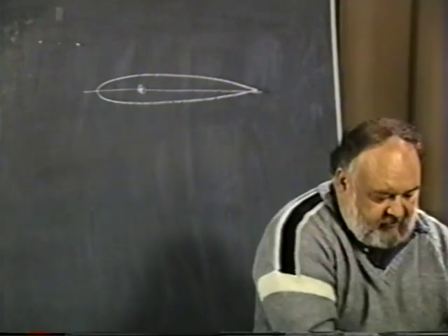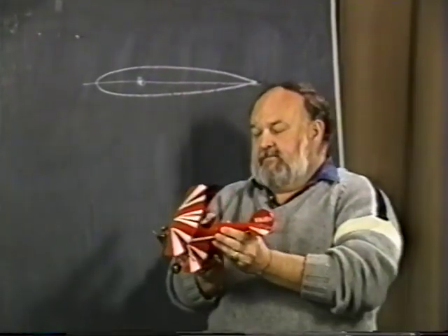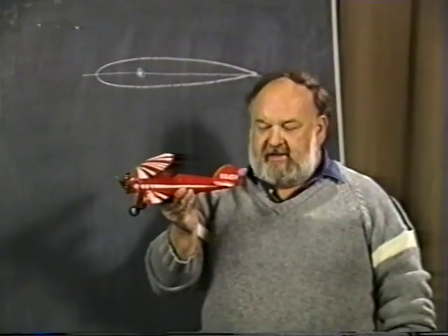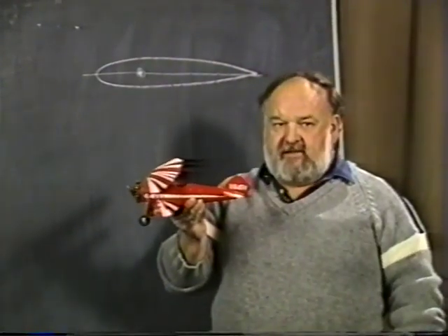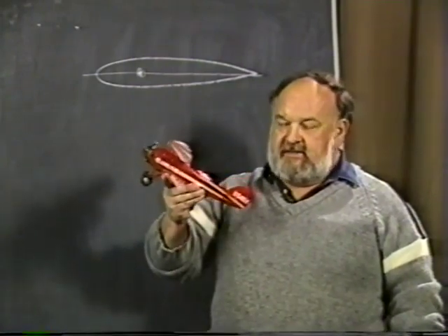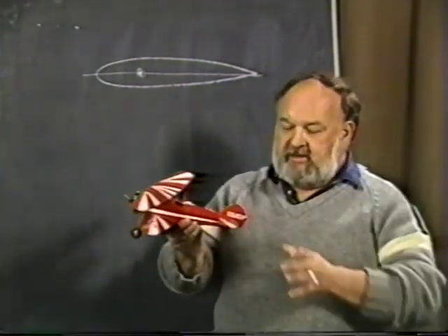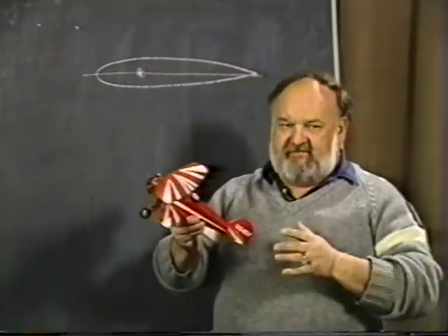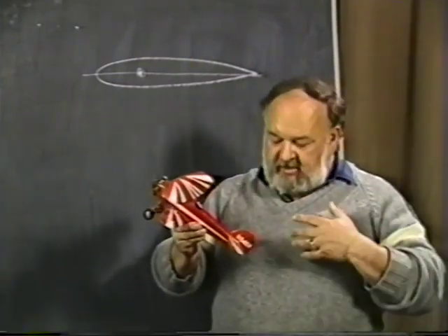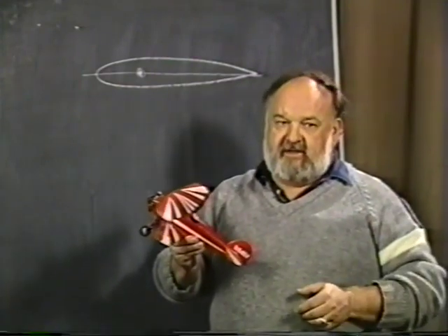airplane. Even though this is a beautiful biplane, imagine that this was an all-flying tail back in here. If you have it hooked up now to the stick and you're flying along and you hit a gust, since it is right on the quarter chord, that tail will not move. It'll stay right in the same position no matter how extreme you go. Obviously, if you go to the point where the tail will stall, then something different happens.